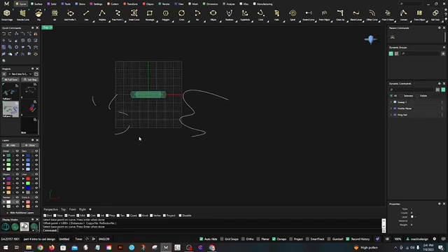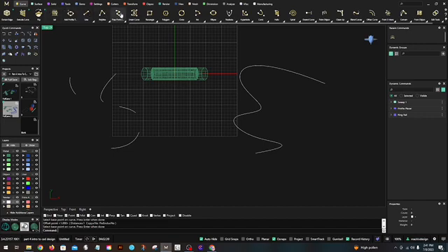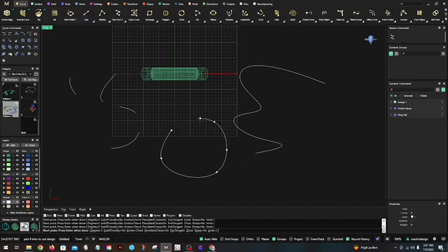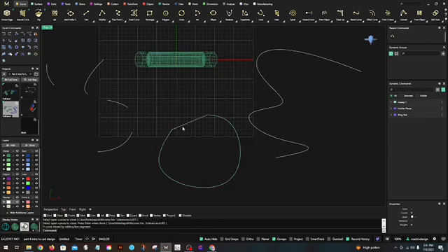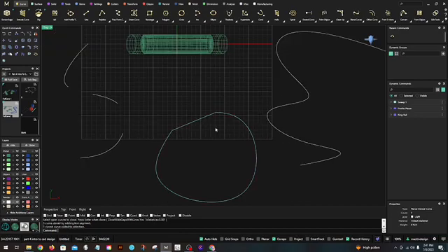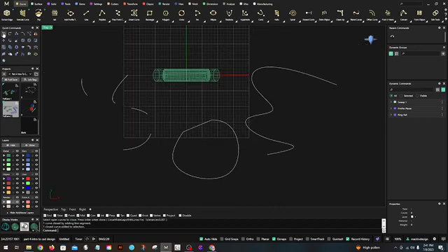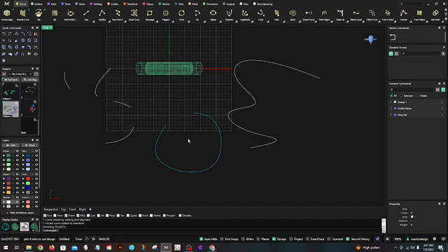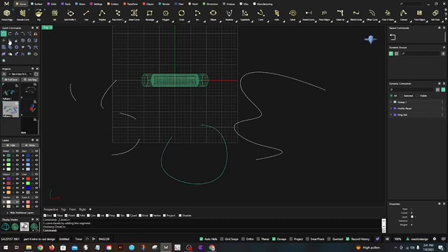Okay, close curve. All right, let's do one that's almost closed. And we're going to click on close curve, select open curves to close. I'm going to select this curve here, press enter when done, and look at that. It did close it, and it closed it with a very straight line. I'm going to back up and see if there's an option. Okay, so if I right click, it just activates that. Okay, back up, deselect, right click, select open curves to close.